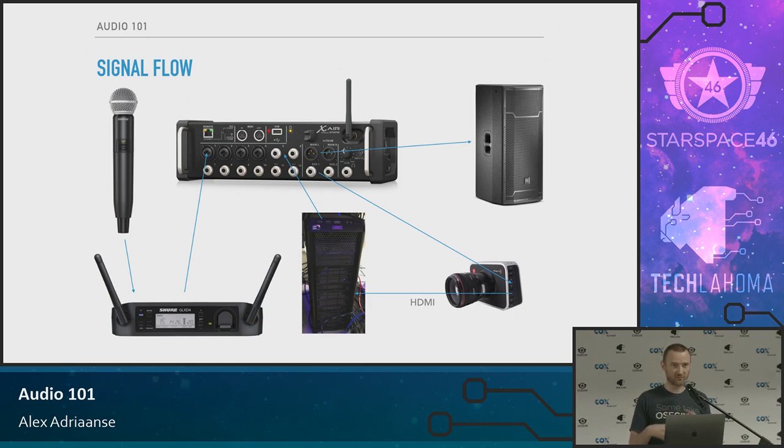So that way you don't amplify a bunch of noise in the process. And then at the last stage, we've got the loudspeaker or the amplifier that's in front of the loudspeaker, and you can use that to dial down the volumes to the appropriate levels to make sure it's not blasting your ears. So you want a hot signal going into your amplifier, and then at the amplifier, you can turn that down.